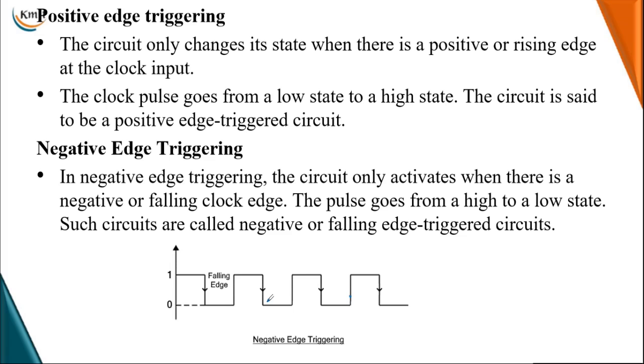These are the basic triggering methodologies which I am going to use on the clock of the flip-flop. Based on this, flip-flops are classified as positive level triggered flip-flops, negative level triggered flip-flops, positive edge triggered flip-flops or negative edge triggered flip-flops.